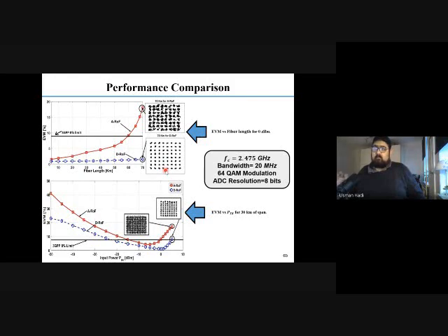So the point is that for digital, the performance is great, even if you see the EVM versus RF input power. When I talk about RF input power, it is the input power that you want your system to use, at which the carrier frequency is modulated. So if it is 8 dBm here, the distribution from -20 to 0 dBm is the power for the analog, while for digital, it is -20 to 8. So you have actually increased the range of power that can be utilized for the digital one. And yes, digital performs better than analog, as you can see with these results.